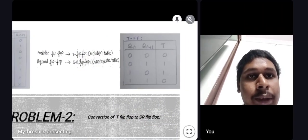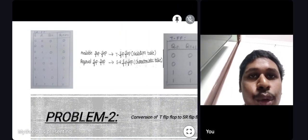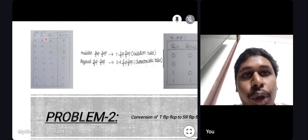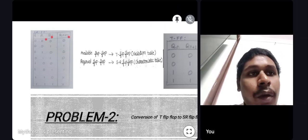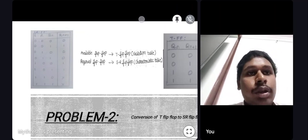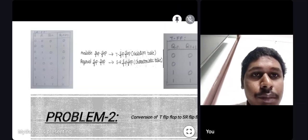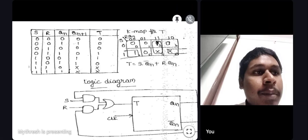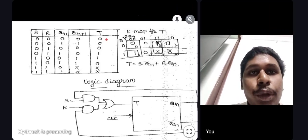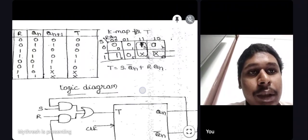So here is the excitation table for the T flip-flop and the characteristic table for the SR flip-flop. In the characteristic table, with respect to the present state Q and next state, we will add the T to get the inputs. Here is the table we require. So here are the toggles with respect to Q and Qn plus 1. To get the equation, we have to do the K-map.